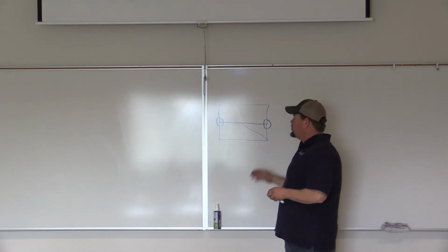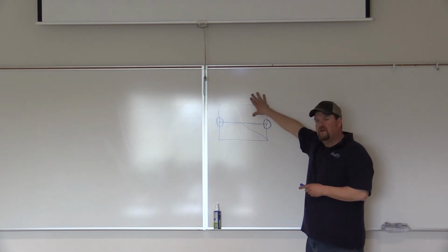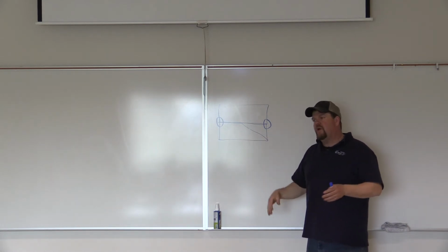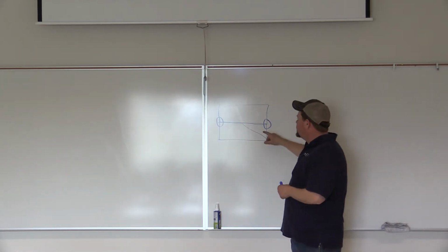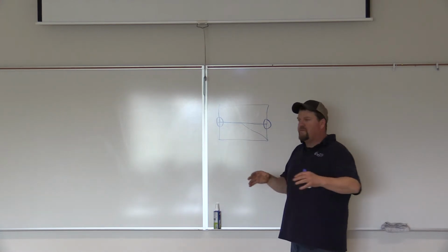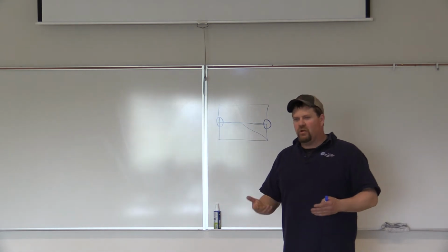For a visual inspection, what happens is, this is the main piece that's going to be hard to fix, okay? So you put a 1-inch block, or they call them a bumper block, or something you can throw on them. And when you're walking around that plow at the beginning of the shift, you're not always looking at everything to 100% specification. But this is really easy because, number one, they're big, and you can look down there and you can see if that's worn down, and you just know to look at it.